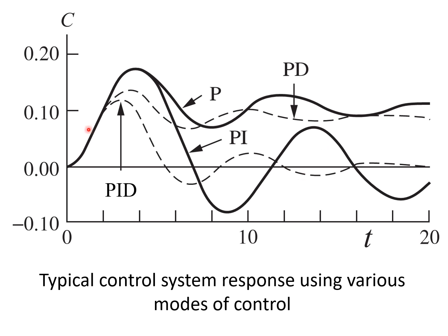But again, you have to decide on what criteria. You have no offset for both of them, but how does this response go before you get the no offset? You get a lot of oscillation before you get no offset, so you get less oscillation before you get no offset. Sometimes we may have a lower overshoot but more oscillation. Sometimes you have a high overshoot but less oscillation. So you have to decide using all the different criteria, using dynamic and even the steady state.